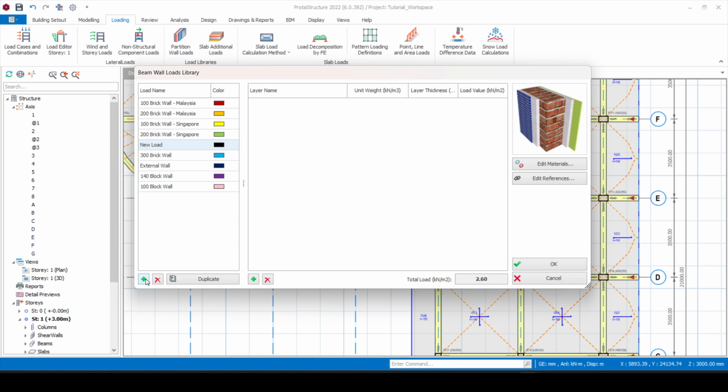Simply click on this plus icon. We are going to get this new wall that's here. You have the option to rename that. So let's rename that, let's say 225 millimeters walls, just like we use in Nigeria. You can change the option if you want. So let's say maroon, or let's get a blue color. I actually prefer to go with the blue color. It's just a color, it doesn't affect your design or anything like that. So here you have blue.